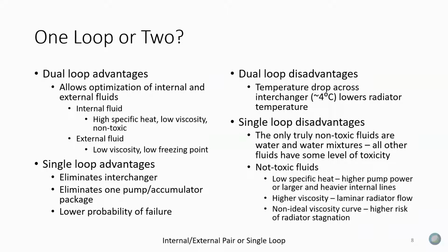These things also have higher viscosity. And if you've got higher viscosity than the Freons or the HFE 7200, it's very difficult to get turbulent flow in the radiator. And it works out that we'd love to have turbulent flow in the radiator to keep the temperature drop between the fluid and the surface of the radiator down. So it's harder to get turbulent flow.